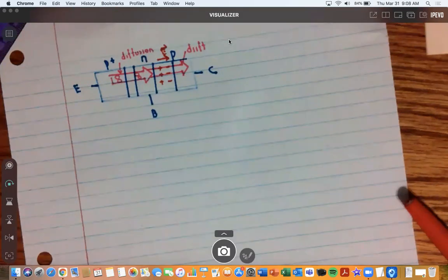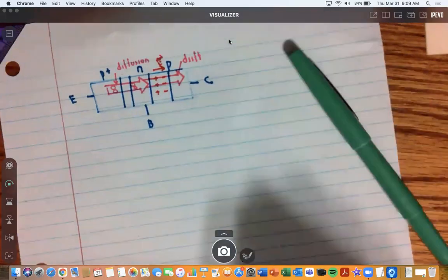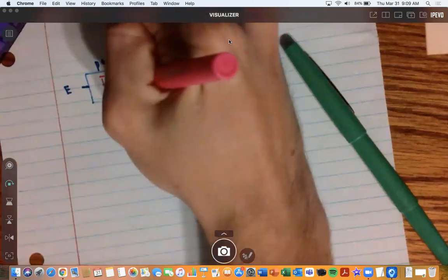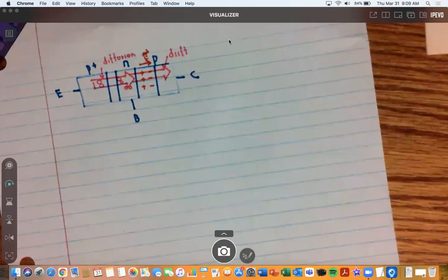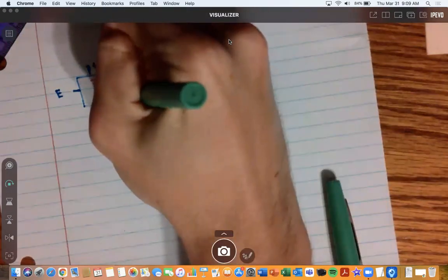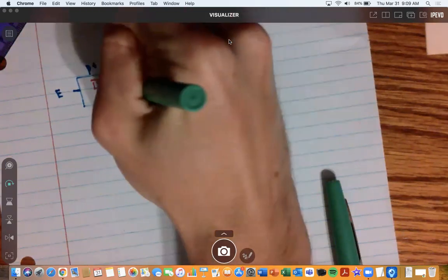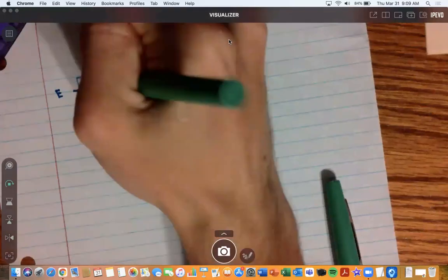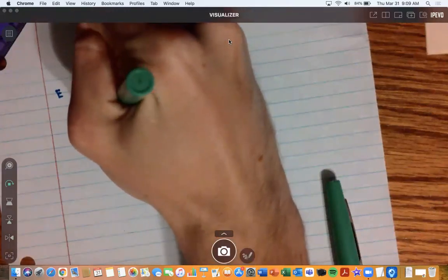The electrons are going to go from the base, and some holes drop down here in the base region from the diffusion. Not all are going to go through the drift process. So some of the current coming through the base is going to go up for recombination, where we might see an electron combined with a hole. And then the other current is going to go here.